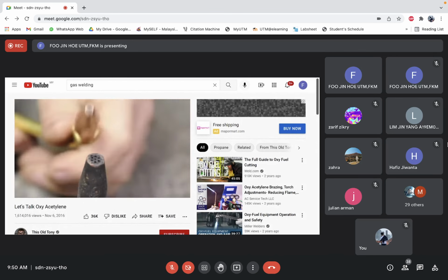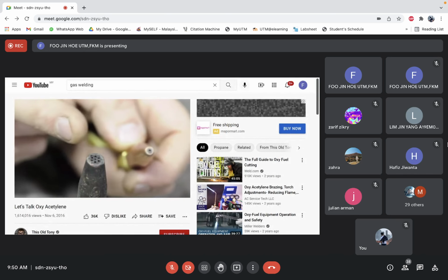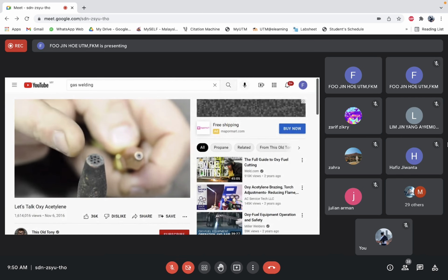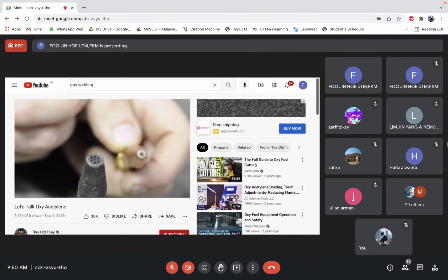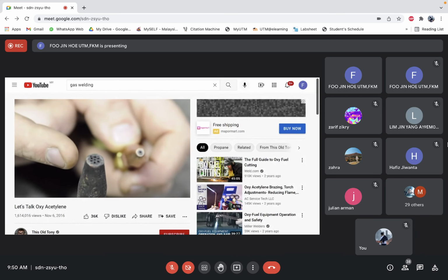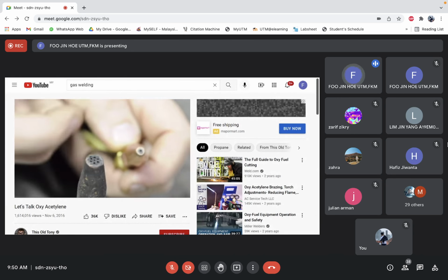Let's take a look at the difference between a welding head and a cutting head. A welding head has only one orifice on the center. A cutting head has a lot more than one. The 6 jets around the perimeter are the preheat flame. That's where your heat's coming from. And the jet in the middle is oxygen. That's what will be doing the cutting. The reason this has holes all the way around that center hole is to allow you to move in any direction with the torch. Like you can cut a circle by standing in one place without having to walk completely around your workbench.